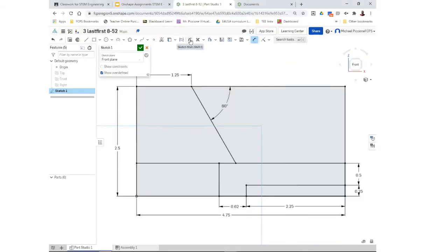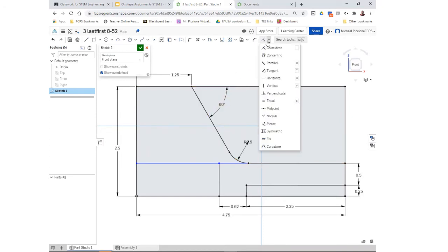So I'll go ahead and do that now. Sketch fillet. Angle to surface, and dimension is 0.5. And since it trimmed that line out, we'll have to just go ahead and draw it back. And if we need to, we can say those lines are all horizontal.